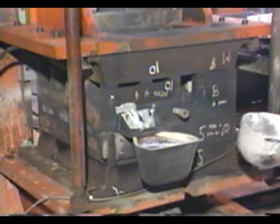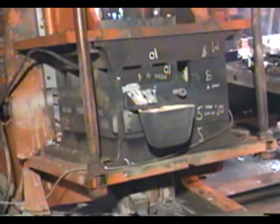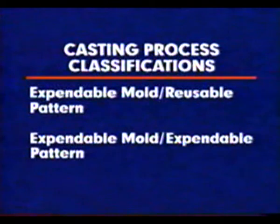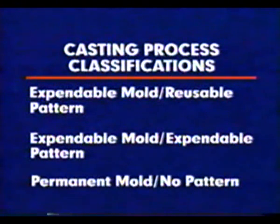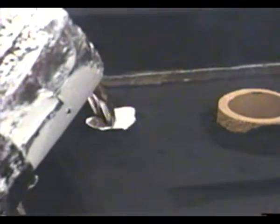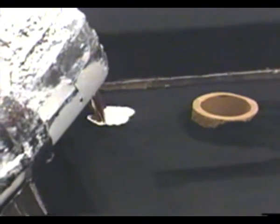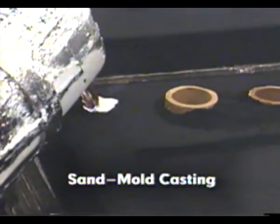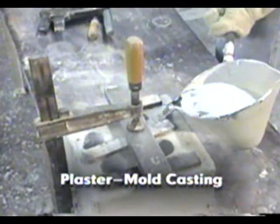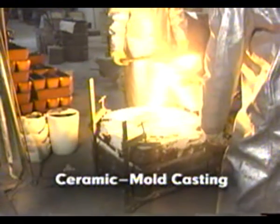Casting processes can be grouped into three classifications: expendable mold, reusable pattern processes; expendable mold, expendable pattern processes; and permanent mold, no pattern processes. Expendable mold, reusable pattern processes include sand mold casting, plaster mold casting, and ceramic mold casting.